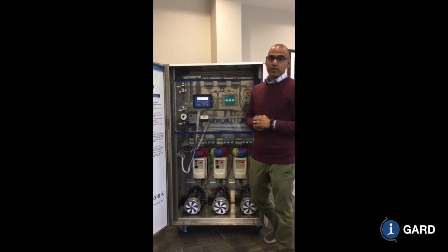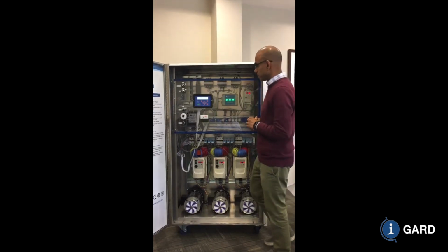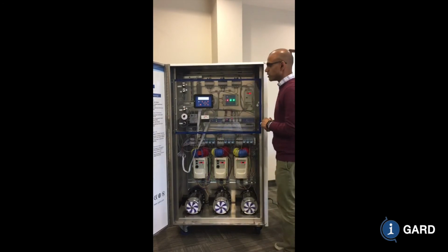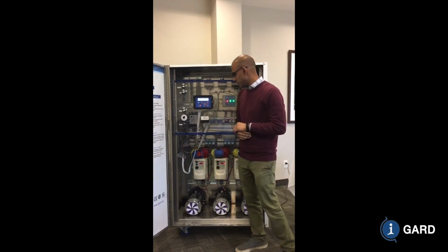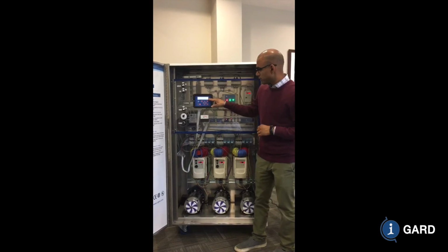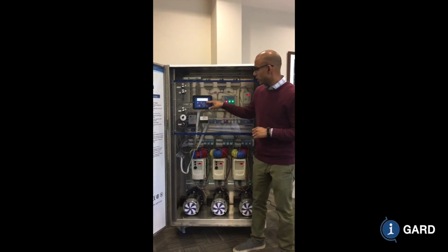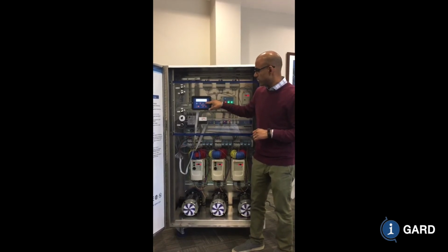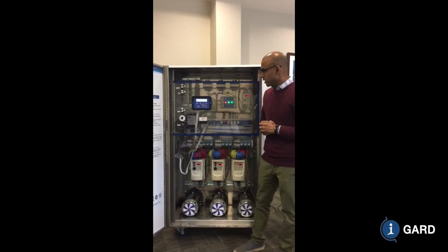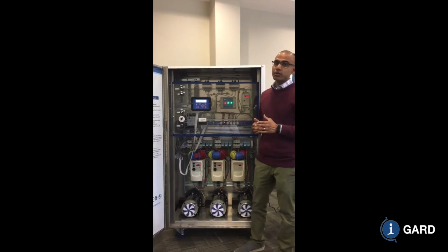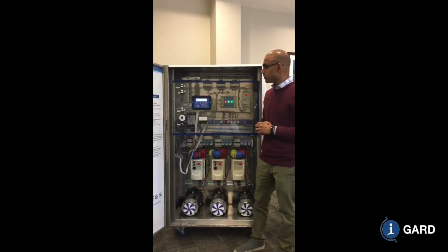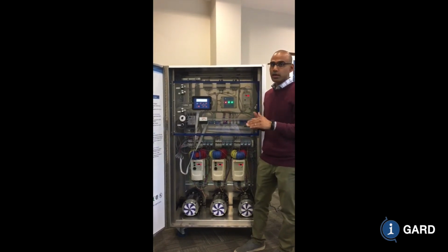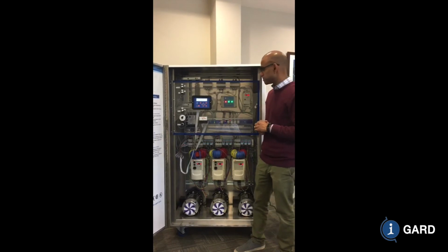So let's have a look at how the system behaves when you have a fault on. I'm going to put a fault on the system. This is a fault on feeder 1, phase A, and you can see that the page says fault phase A, feeder 1, and it tells you the IG ground fault current level, which is 81%. This percentage is given as a percentage of the let-through current. In this case, I have a 1 amp NGR, so the percentage that the DSP shows you is a percentage of that let-through current.